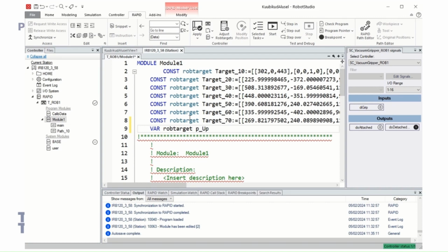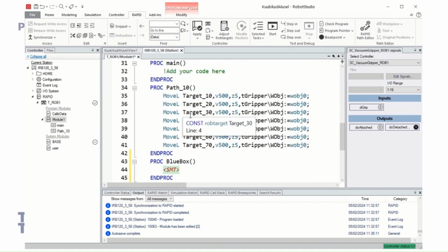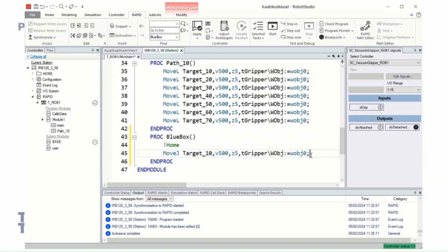Like this, and we don't need to add any values in here at the moment. So now we go back here. I would take first this home position motion here, copy it and place it here. So home, I would use J motion because we don't know exactly in which direction the grip tool is oriented. So then we do the calculation.